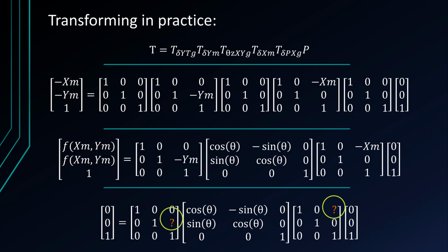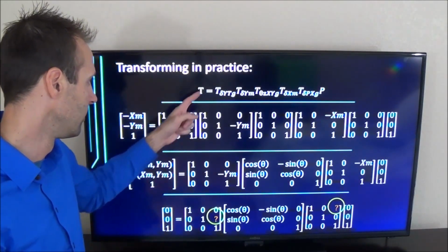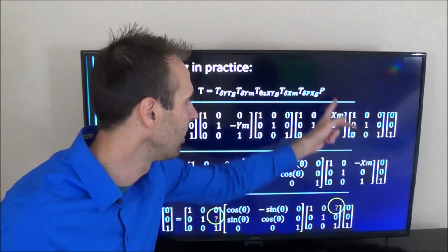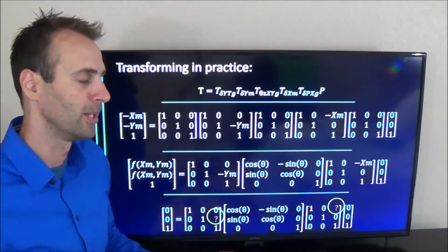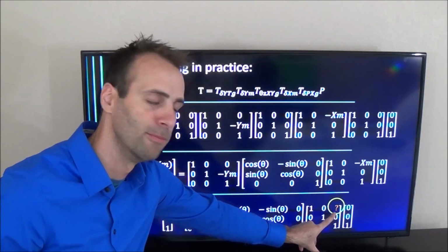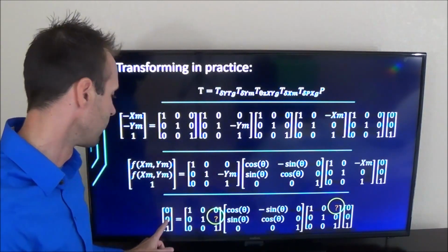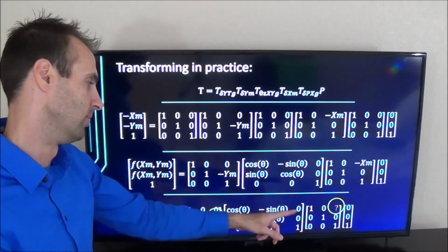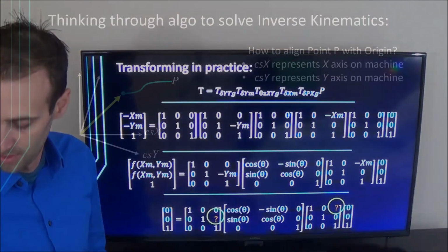And then that basically looks like this. If I know my tool coordinate and I know my part coordinate, what do I have to do to solve this equation? And that means how do I have to move my X and my Y to align these two points in space with a certain orientation, mind you.